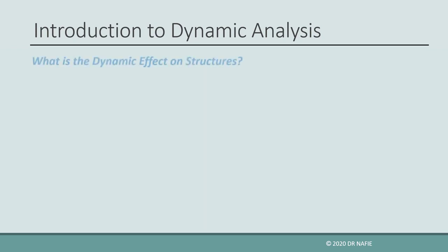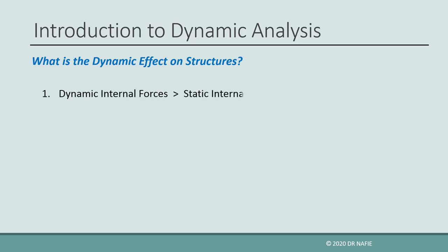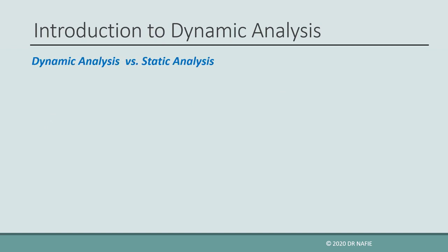Dynamic forces will have two possible adverse effects on structures. Number one, the internal forces generated due to the sudden dynamic force are larger than that generated statically. In some cases, the dynamic internal forces are more than twice the static forces. Number two, the vibrating forces that are continuously acting on the structure can cause fatigue failures.